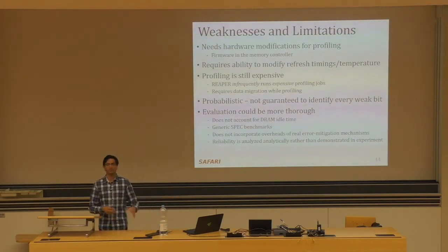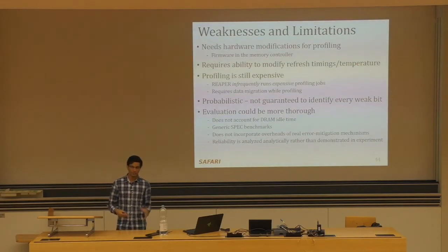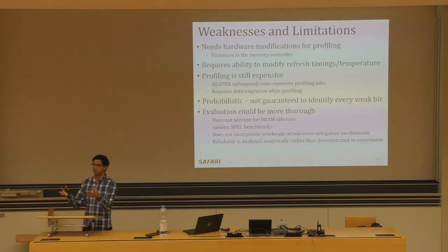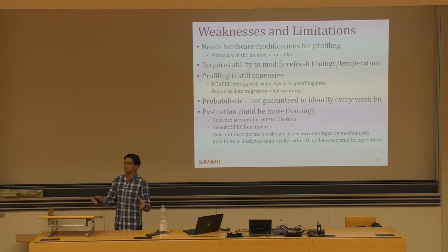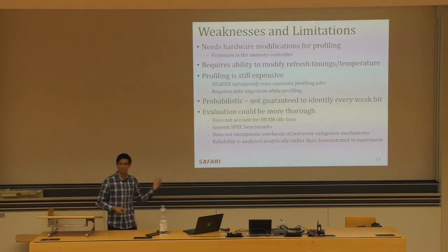Right, so for example, if we go back to that RAIDER example I gave, we're refreshing different regions of DRAM with different refresh rates, right? There's some cost to that. We have to do some lookup to see what should be the right refresh interval for this region of DRAM, and I have to do some sort of analysis to figure out which regions of DRAMs fall where. All of this comes at additional overhead, and that overhead is not encoded in this performance analysis that we did here.